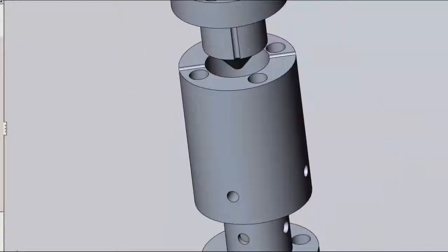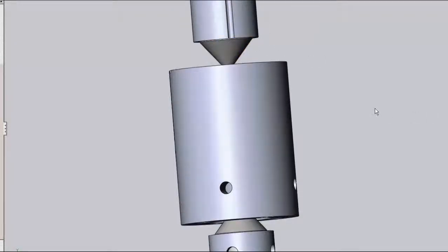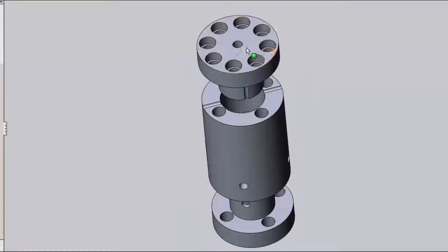The anvils themselves are made of tungsten carbide, so you can see them here. I counted them for the model. This anvil cell was made specifically for these anvils with these dimensions. So the entire model had to make sure that these anvils fit in here, given the maximum constraint on the diameter because of the probe size.